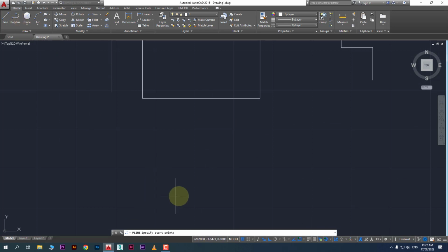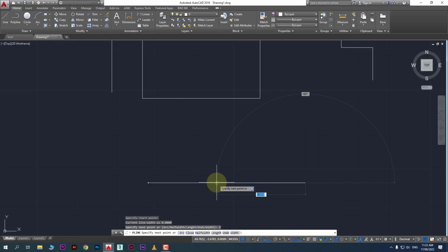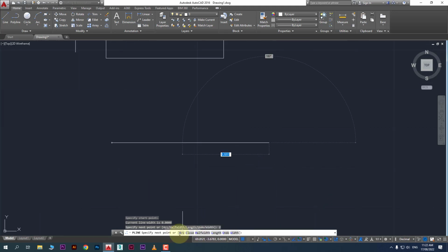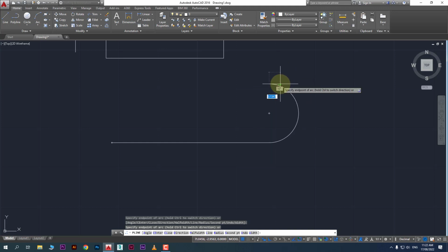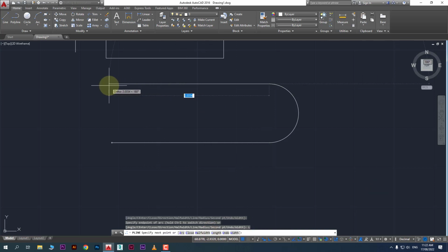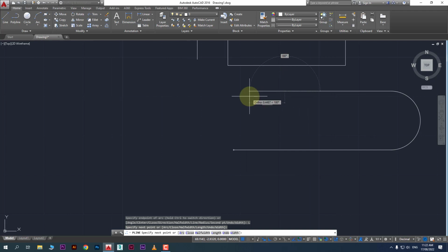Take the polyline command and click somewhere. Okay, and now you can define the length. For example, I have 2 units length. Right, now look here, we have many options in polyline. So you can also start an arc from this point. If you want to start an arc, click on arc or press A, because A is highlighted blue. Click here. Now you will see the next segment is converted into an arc. Click here like this. Now you want the next to be a line. Okay, then click again here on line or press L. Then you will see it's a straight line, right, like this.